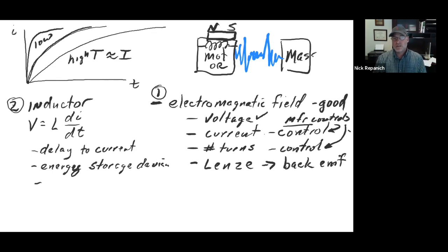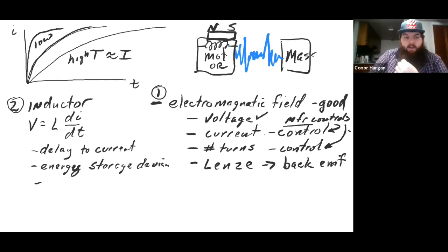It's exactly, you don't necessarily choose it directly. You're probably choosing it in the form of the speed torque curve has high torque, low speed versus the opposite. And that is what you're matching to your application. So it's one of the things you'll do when you go back and look at your concrete extruder, and you're going to say, all right, is that high speed or low speed? Do you have a high speed or a low speed application? Low speed. Low speed, right.